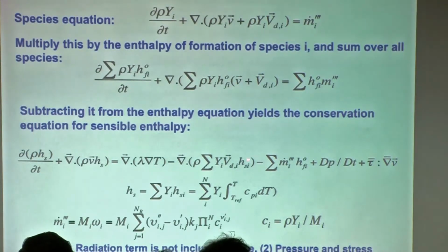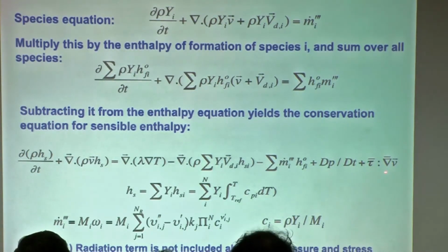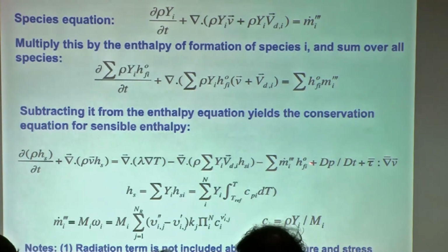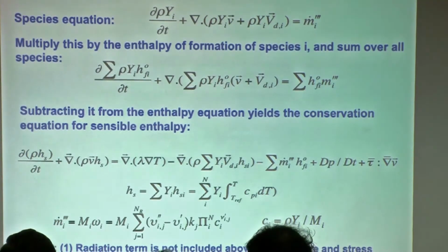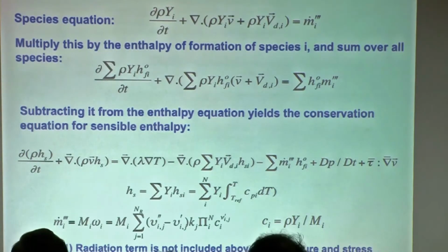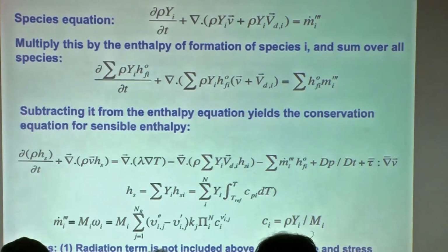In normal combustion and reacting flow analysis, the software does not have this term, unless there is a special situation. So for the flames we are going to analyze, we will not have this term or this term, but the rest of the terms we will have. Whether we consider laminar flames or turbulent flames, turbulent of course gets a lot more complex, because we do not consider Hs, we consider the fluctuating part and the mean part. There is a lot of turbulence modeling involved for turbulent flows. But if you are doing DNS of turbulent reacting flow, then you can use these equations directly.